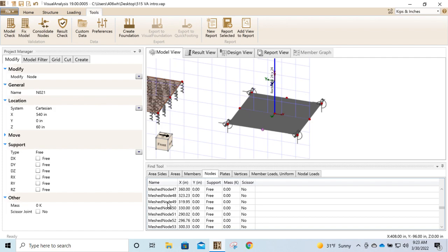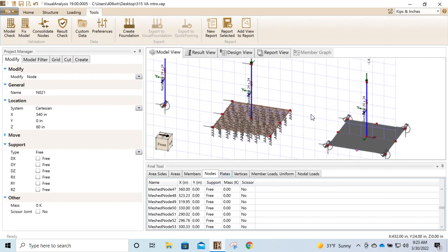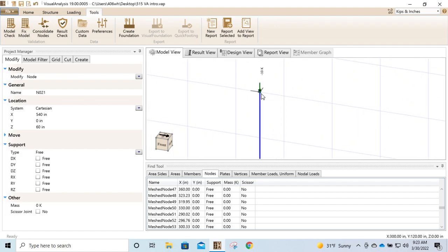I guess I was thinking more about what we were saying the other day, how you could either fix the node or you could do rigid connect on both of the members going into that node. Well, that's different, right? Because fixing the node fixes it with respect to space, right? Yeah. If it's fixed with respect to an element, right? Because right now, if we looked at this node up here, this node I just pinned in the two planar directions, right? But as it relates to rotations or vertical displacements, it's based on its connectivity to this element. It's going to chase this element. This element's going to give it the stiffness.